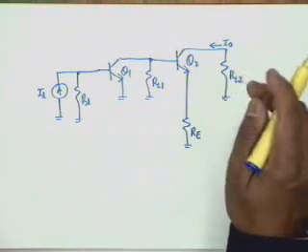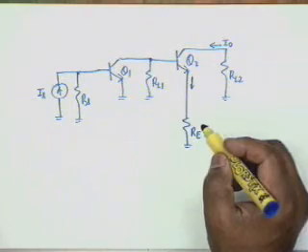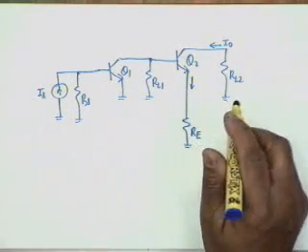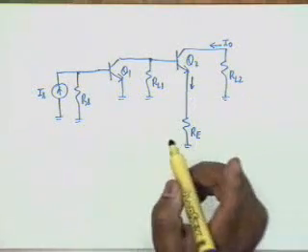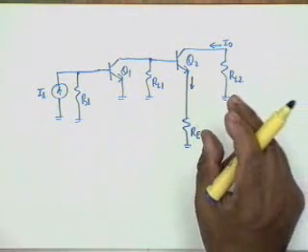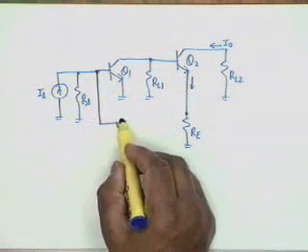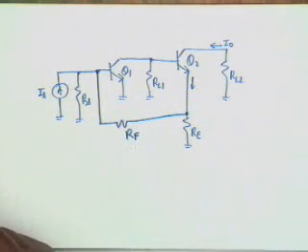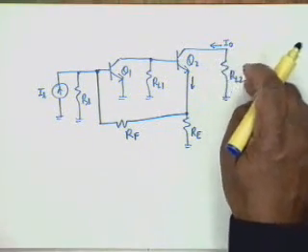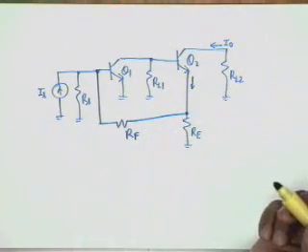Isn't that clear? So what I do is I take an approximately equal current. You know this current, the emitter current, is approximately equal. It's I0 divided by alpha, where alpha is approximately 1. So I sample this current. Now I don't sample the current as a current. I use a small resistor here to drop a voltage which is proportional to the current, and this is what is applied here through a resistance, let's say RF. If I0 is dependent on RL, so is the emitter current. Right. If I make a connection here, obviously the effective RL will be disturbed. I don't want to do that. So I use a small resistance here and make this connection here.